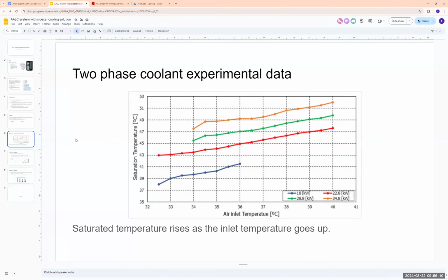Yeah, and it's just larger contact area between the coolant and the metal. It's much more efficient than the fin and tubes. The tubes are a very old technology, but you can use copper for copper cold plates. You can use a microchannel with aluminum, but some customers don't want to use it.